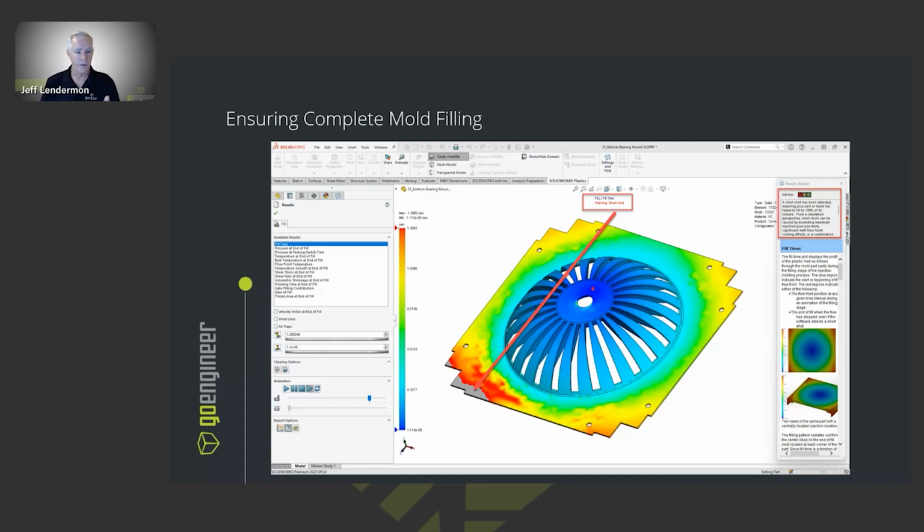One of the things that I always look at is wall thicknesses. It may be a case where the designer was trying to see how light he could make the part, and then he chooses a wall thickness that that material will not flow through very well. If that material is what is specified, then we may have to change the wall thickness. We can compare polymer grades and find a material that may flow easier, or we can adjust wall thicknesses. So in this case, I'm going to choose to adjust my thicknesses.